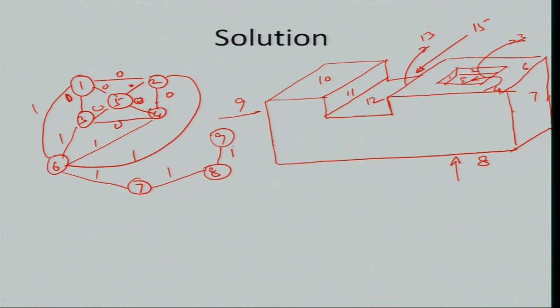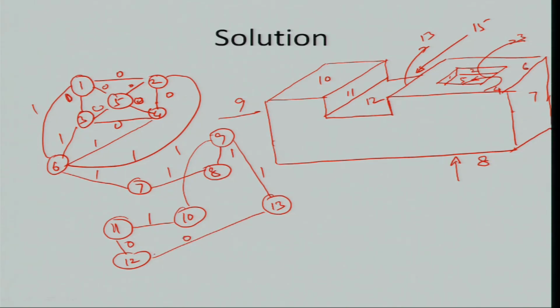So if we look at, let's say, the 9th and the 13th and the 10th surface. So you have 9, 13, and you have 9, 10. So these are both connected through convexities. 10 and 11 obviously would again be connected through a convexity, but between 11 and 12 you are having a concavity, and similarly between 12 and 13 you are having another concavity, and the 13th surface finally is also connected to the 15th surface with a convexity.